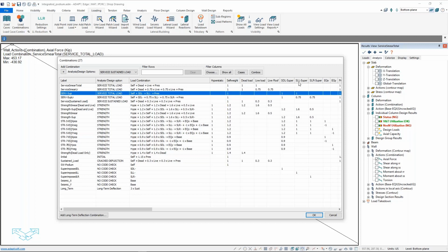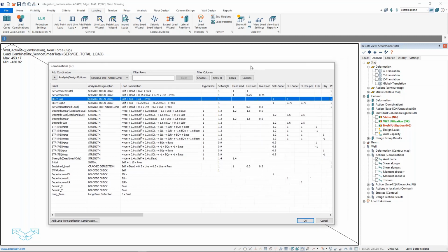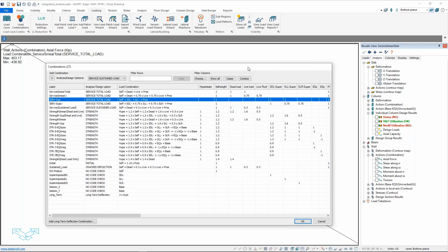These are the smear loads, and under self-weight and dead load were the individual line loads. It was a little bit of a pain initially to handle the two, but we maintained both sets of loads because they were in the model, and we just repeat each of the load combinations to account for both. So in effect, we're designing for the envelope of that loading combination in this particular example.